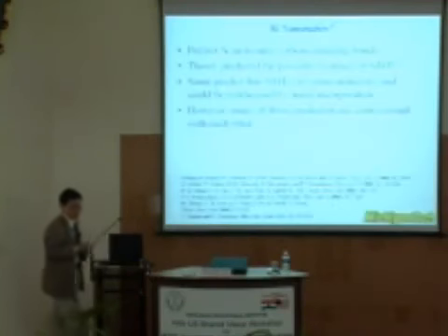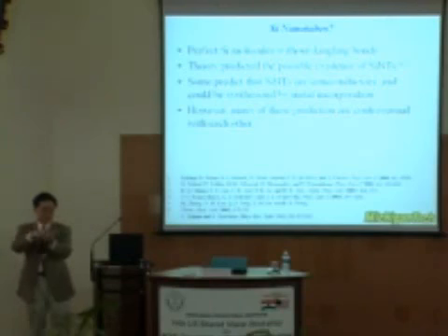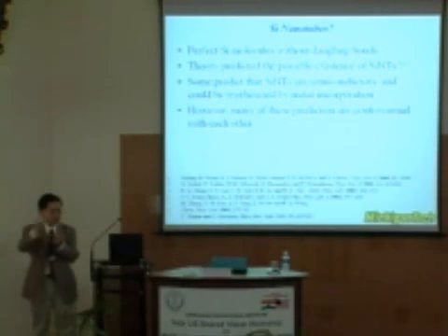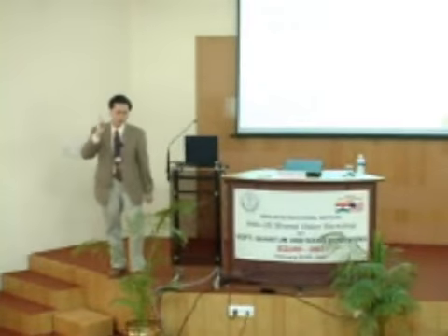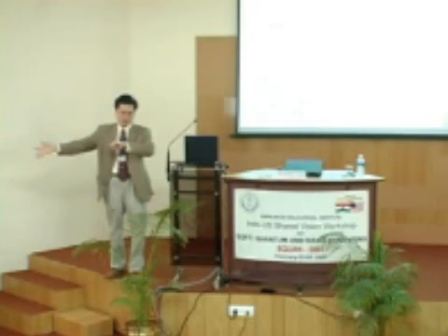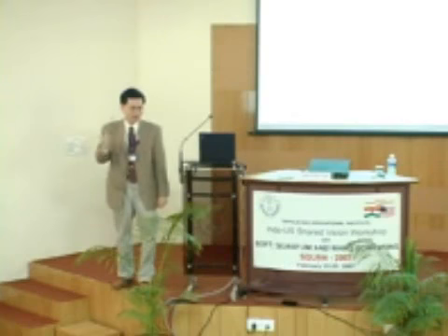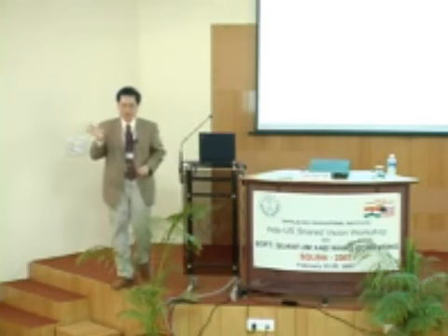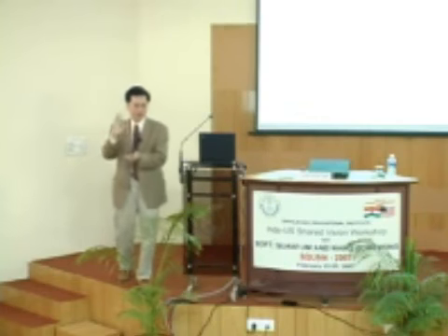However, should we consider silicon nanotubes? Why? Nanotubes are perfect. There's no dangling bond on the surface, just like what I've shown you on carbon and silicon, right? So in that case, you don't have to worry about surface damage or vacancies and scattering, right? However, if you think carefully, you see graphite, a natural product from the earth. You have diamond, sp2, sp3 bonds from pure carbon. Silicon, you have only silicon crystal, which is a diamond structure. You will never see silicon in sp2 structures like graphite. So which means they can never form tube structures without defects.